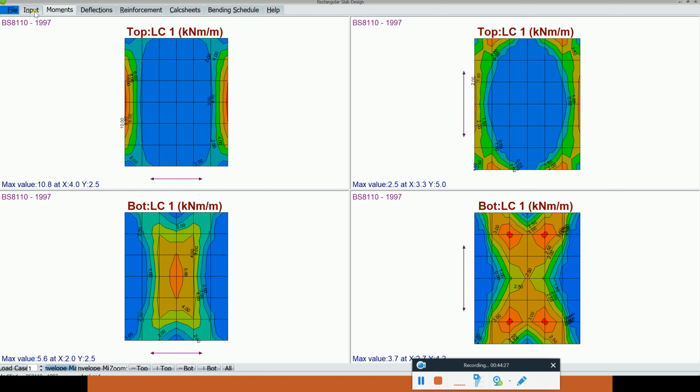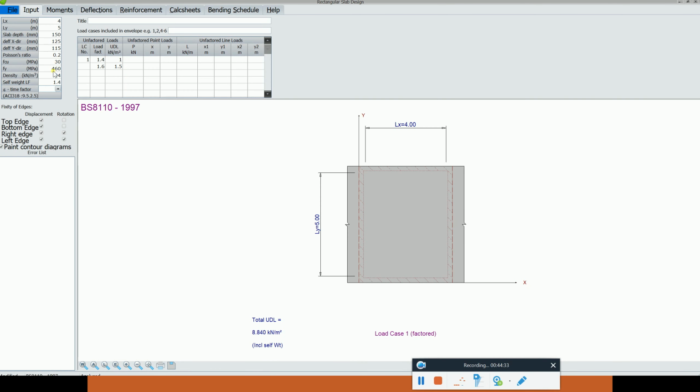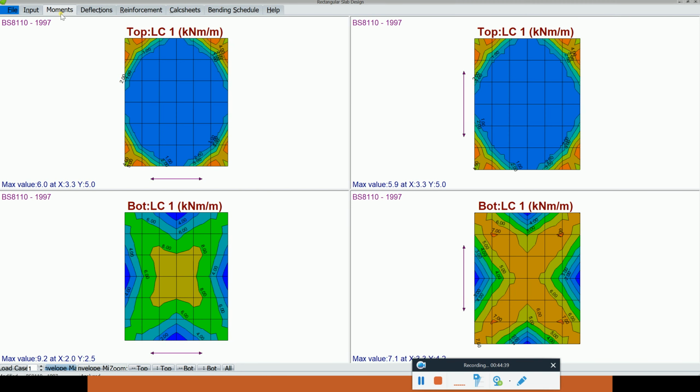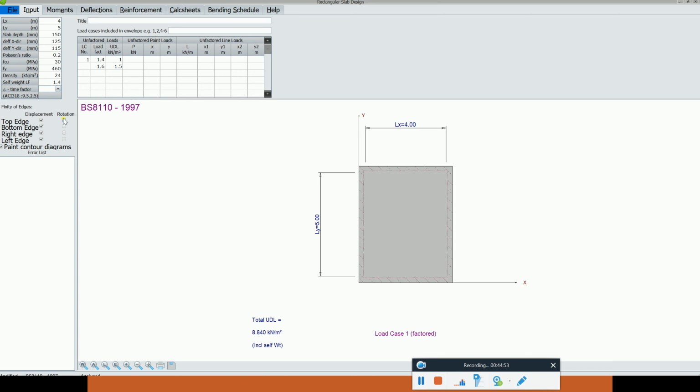Now, if we go and apply, let's say no bending moment, no continuation at all, you can see that we don't actually have it in these particular zones. In each zone, the only thing we have is the column portion. That's a bending moment in the column portion because it's representing a flat slab system, since there are no beams.